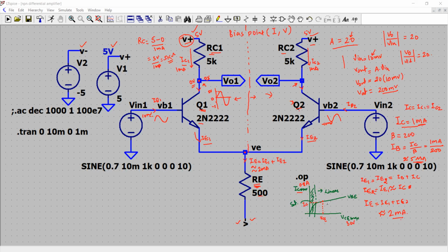So you want to make sure that you operate at this bias point. So you need to get the values of the correct current. Here you are saying I have a value of 1 milliampere for the current, and now you want to determine what is the voltage across the collector to emitter of this transistor.